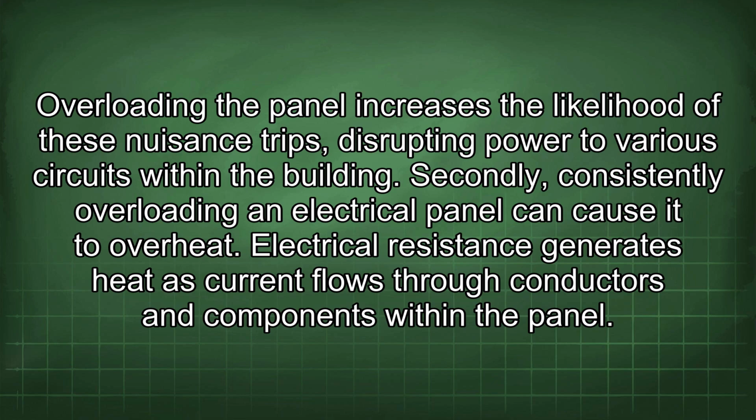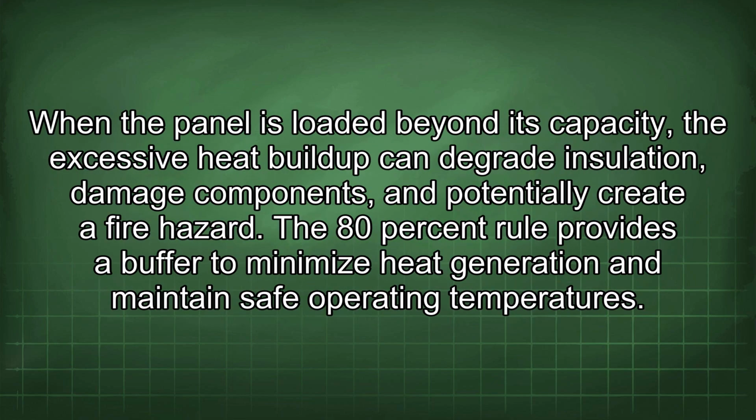Secondly, consistently overloading an electrical panel can cause it to overheat. Electrical resistance generates heat as current flows through conductors and components within the panel. When the panel is loaded beyond its capacity, the excessive heat buildup can degrade insulation, damage components, and potentially create a fire hazard. The 80% rule provides a buffer to minimize heat generation and maintain safe operating temperatures.